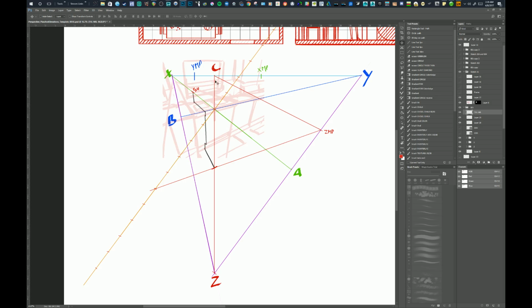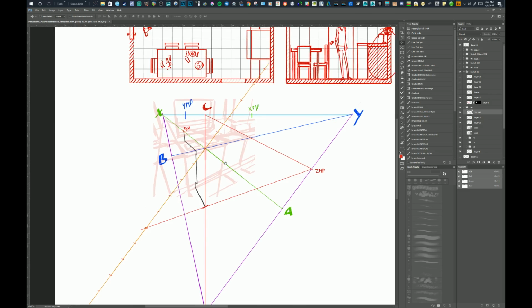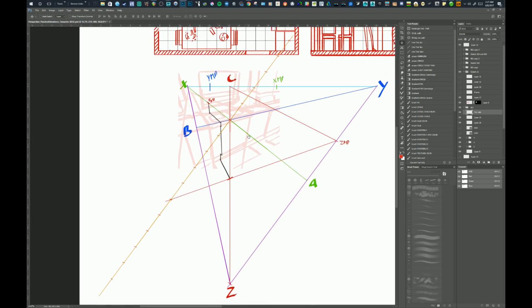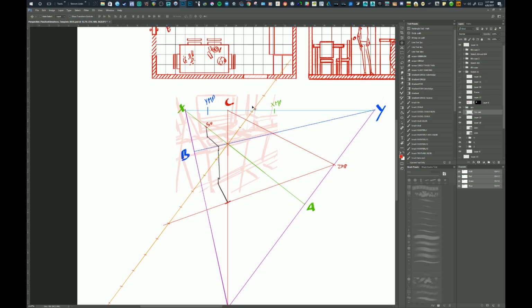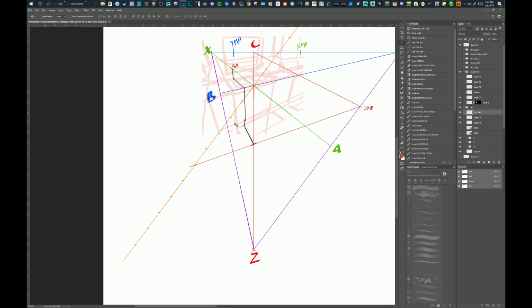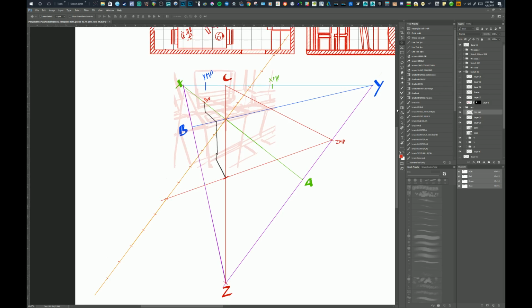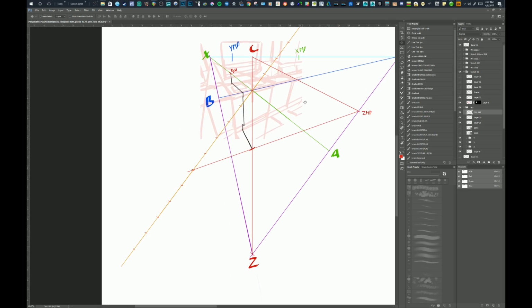So we can now extend our reference line to accept these units if we so choose. We don't need to, though, because everything that's inside the view right now can be calculated from these few units here. And we don't need anything more than 5 units down here because there's no need for them. If you notice that this is the ground anyway, so all we need to do is foreshorten 5 units on the ground and then maybe lengthen 5 units up onto that reference line.